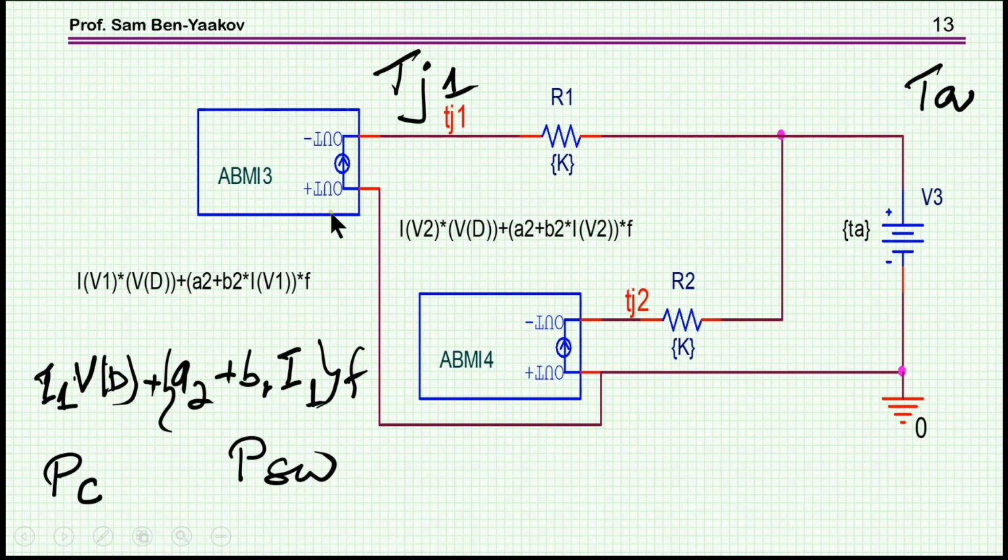And then we have these two transistors with the power passing through there, assuming the same thermal resistance. Obviously, the voltage here will represent the temperature of the junction of this transistor, and this is the temperature of the junction of this transistor.